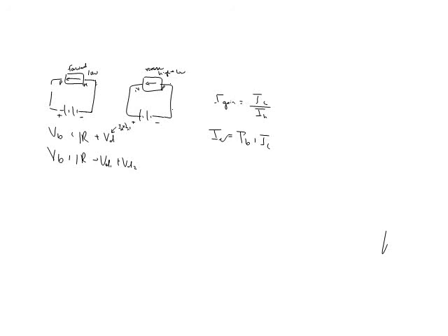So then they put a new protective layer on there with a different set of holes, put it back in the chamber, and add the next layer of dopants. Take it out, pull the wafer off. So now you can think of it as printing little tiny diodes and transistors on there. So to have a diode, it needs to go through the process twice at least. And then for the next one, for a transistor, you have to go through at least 3 times. So that you end up with layers of transistors and diodes.